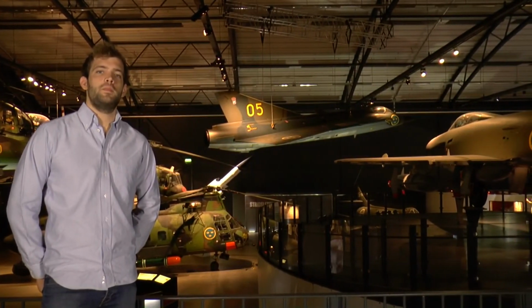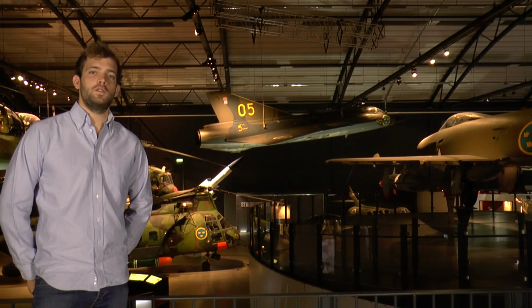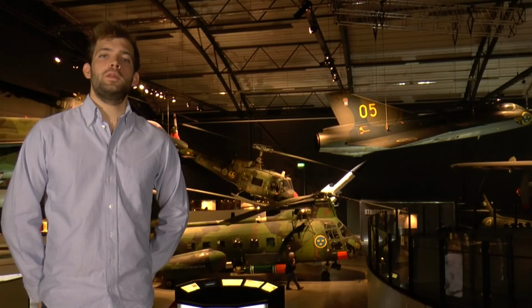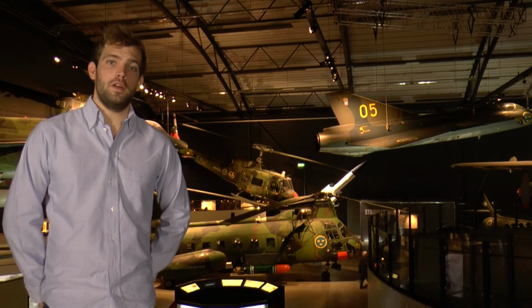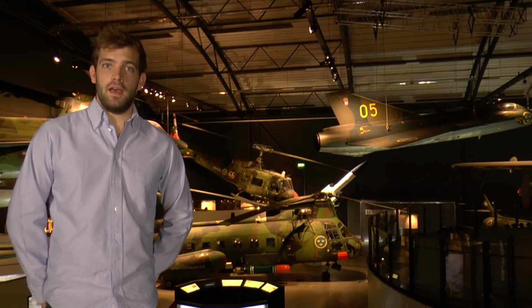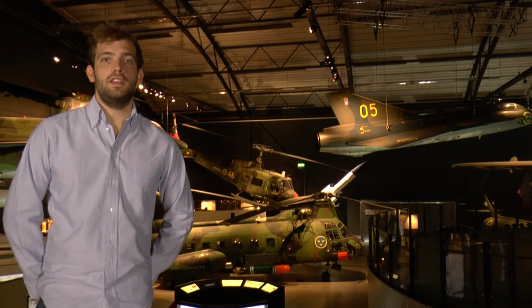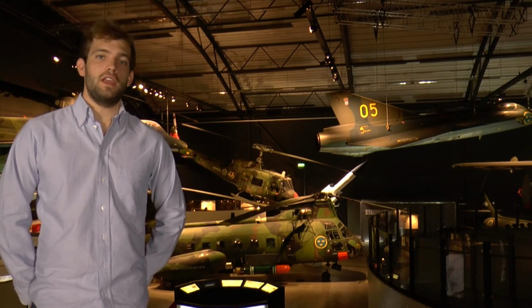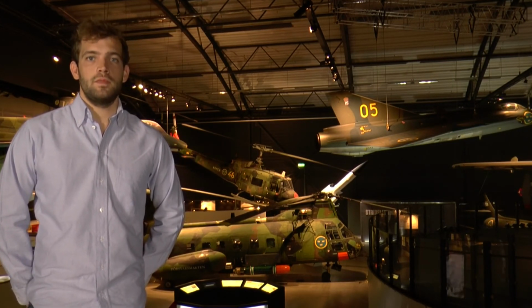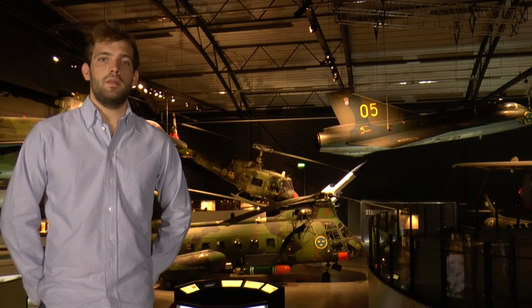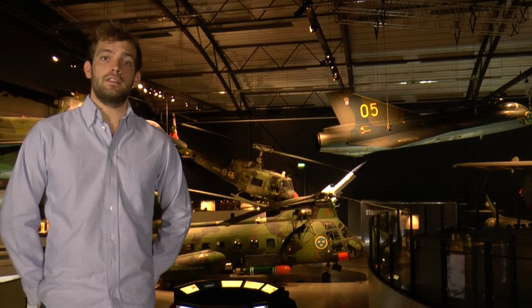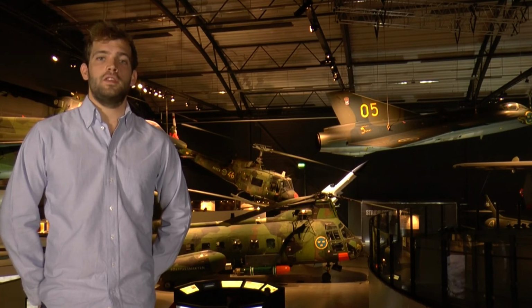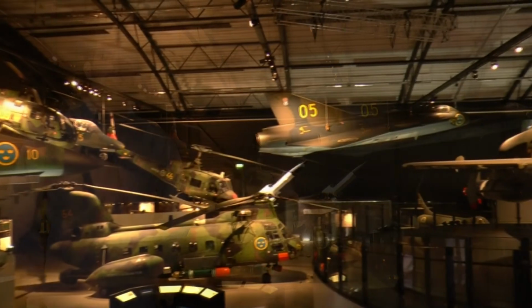In order to wrap up today's session, I would like you to recall the key elements of today's video. The main purpose of axial turbines is to extract energy from the airflow. This is done by a consecutive set of stages, each consisting of a stator and a rotor. Sizing those components is done by using velocity triangles and the angles alpha and beta, which serve as major design parameters.